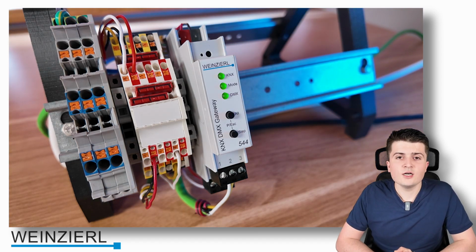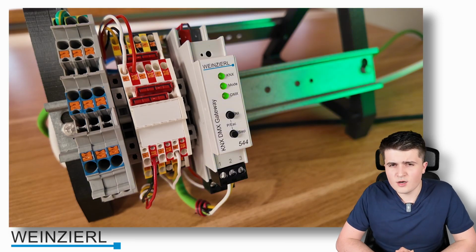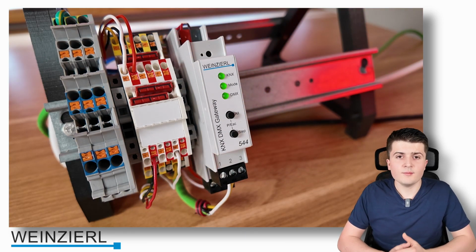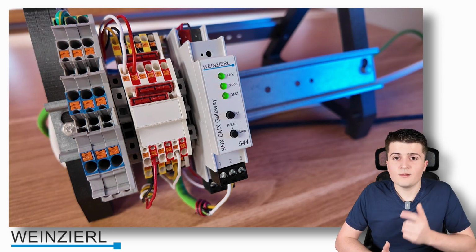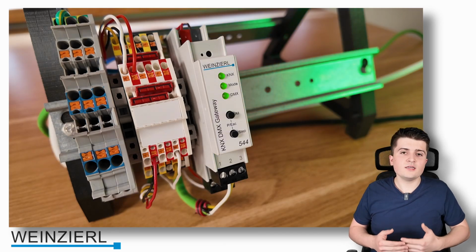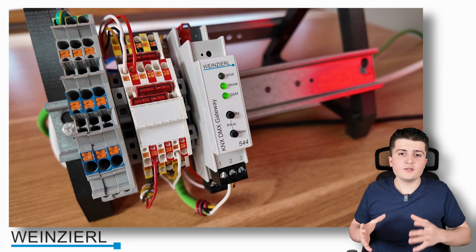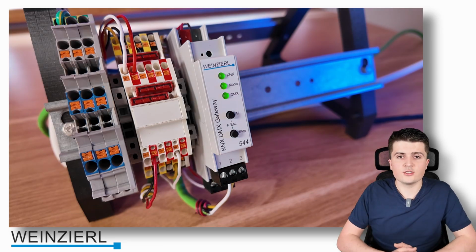And besides that, we can see that on the top of the device we have 2 push buttons, which are pretty important, because with those we can first of all set the device into programming mode, but we can also use them for manual control, and this is really a handy feature after you have installed the device, because with that you can easily check if your installation is correct.